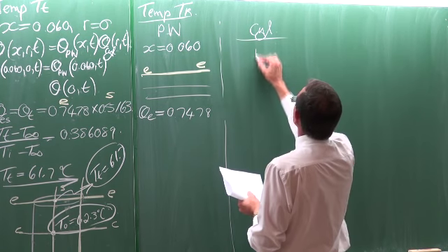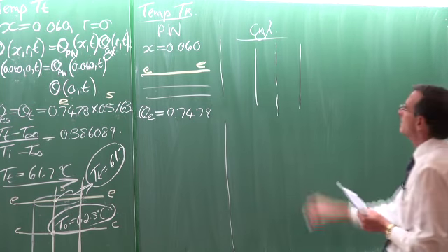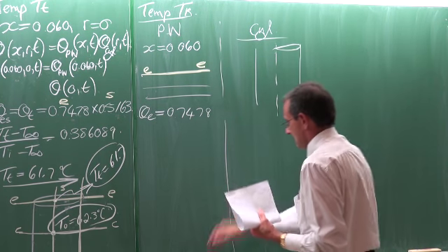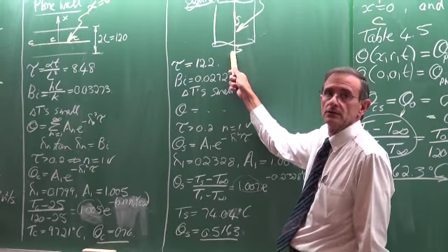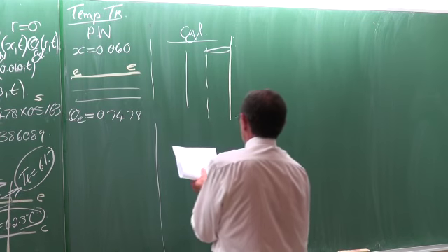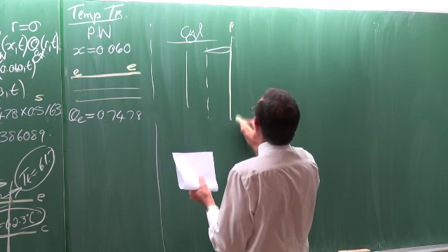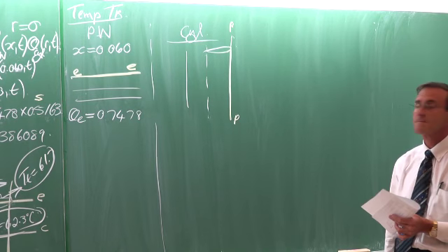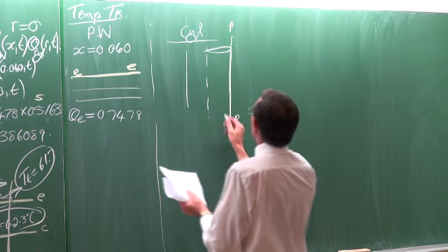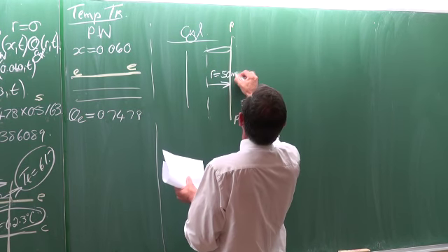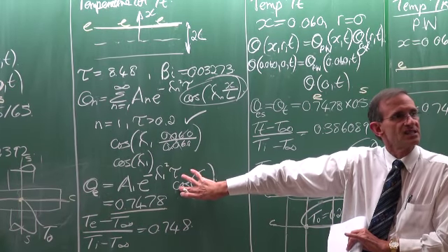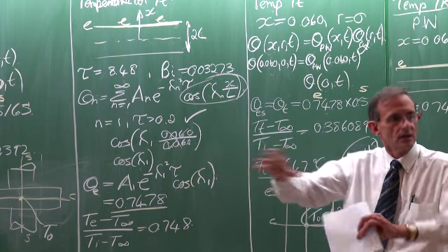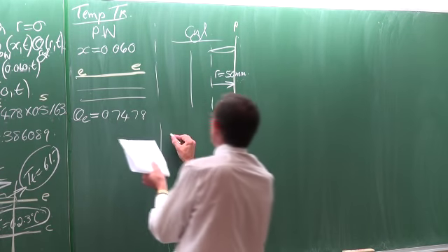Now for the cylinder, previously we've looked at the solution, let's just go back to the cylinder again. The solution was on this line there. Okay, so now we need to get to that line there. That would be the solution for the line there, and let's call it the P line. So now we need to get it for a radius of 50 millimeters. And just like before, this term is going to pop up, in this case with some J values, the Bessel function values. They're in the table, or you can solve them. And it's going to look like that.